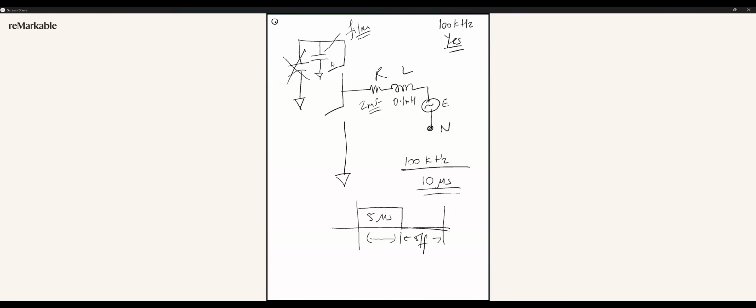But I don't think the power will have any role in capacitor type because it's related to frequency, right? If the switching frequency is high, you can go with a lesser value of capacitance, meaning you can go for a film capacitor, right?